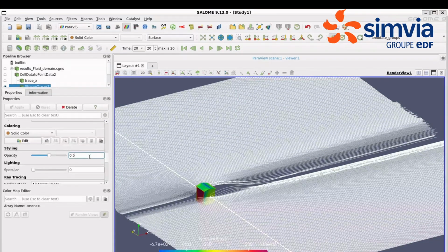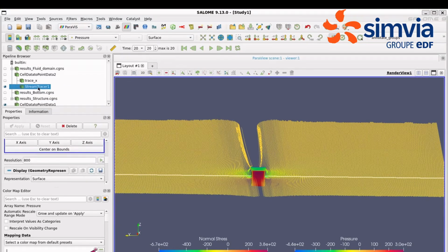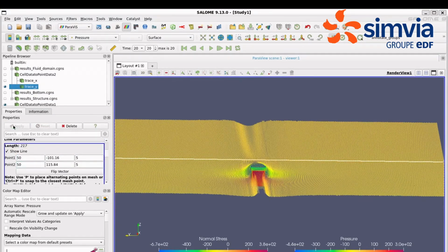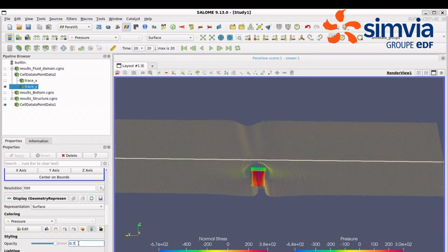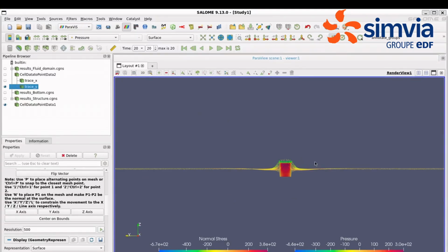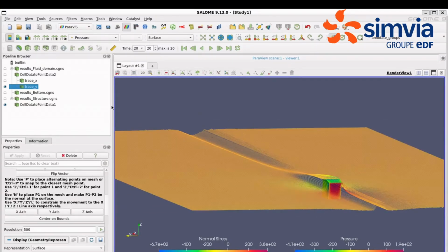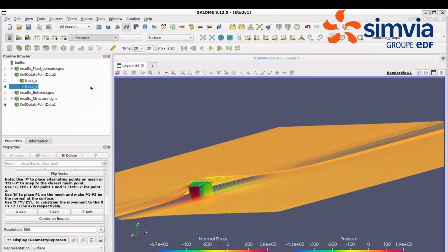Displaying the streamline along this plane and setting their color with the pressure color map allows us to also observe some pressure diffusion effect along the y-axis. Indeed, we still see the maximum of pressure in the side of the house facing the wind and the pressure area behind, but we see the non-zero pressure areas are not exactly before or after the house along the x-axis. Pressure is slightly diffused on the sides.